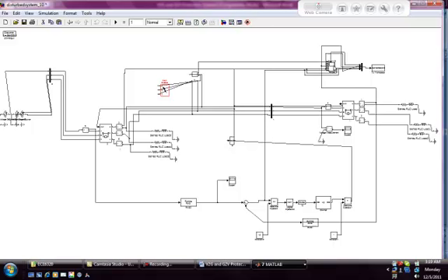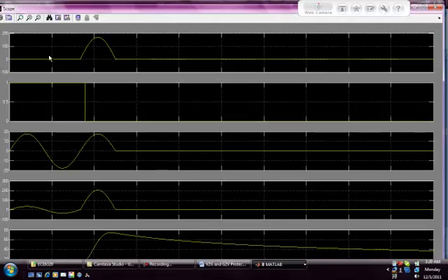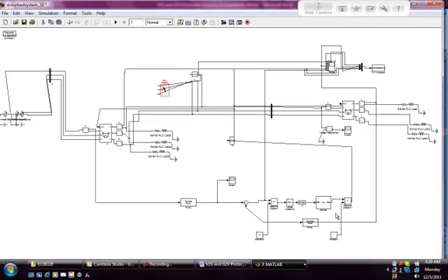The differential relay only checks to see if the two currents add up to zero current. As you can see here, the second plot shows the breaker position of both the EV and the house breaker, which will trip for a differential current. Now the differential current pickup, or the tolerance, will be changing when there is electric vehicle loading.